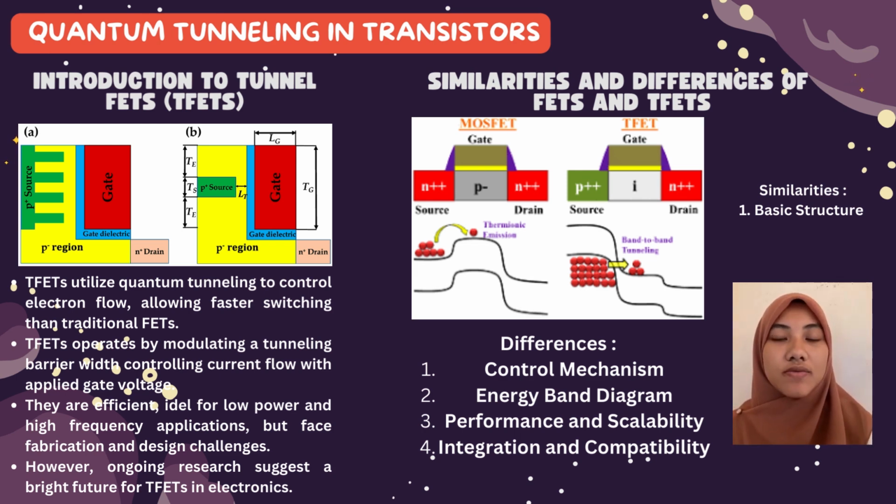Now let's see the similarities and differences between TFETs and traditional FETs. As you can see in the figure, both have the basic structure. Both TFETs and MOSFETs consist of a source, drain, and gate. The gate controls the conductivity between the source and drain by applying a voltage. There are four differences between them.